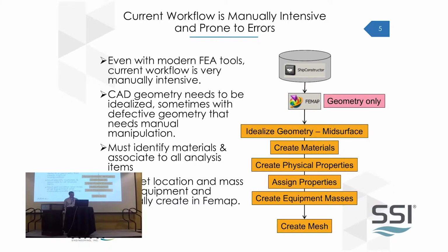Oftentimes once you've created your model, you have to go back and forth between whatever your CAD tool is and whatever your finite element tool is, to make sure that what you built a model of is actually what was in the CAD tool. Also, in the case of these foundation analyses, obviously the foundation is supporting some sort of equipment, so you have to go in and figure out what the CG of that equipment is, make sure you have the CG correct, make sure you have the maximum, and manually create all those things in your finite element tool.